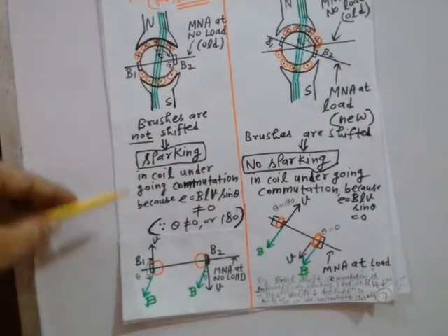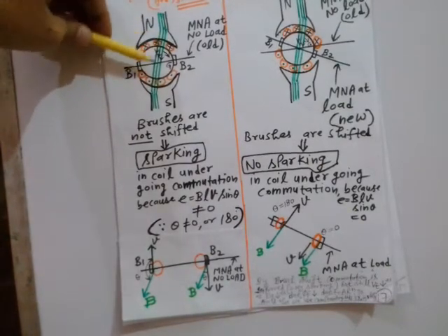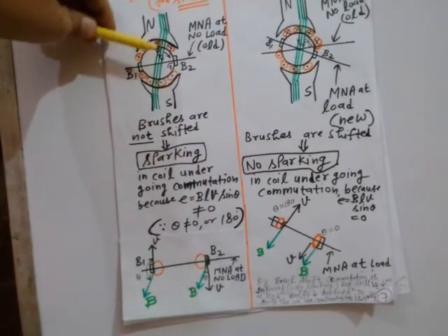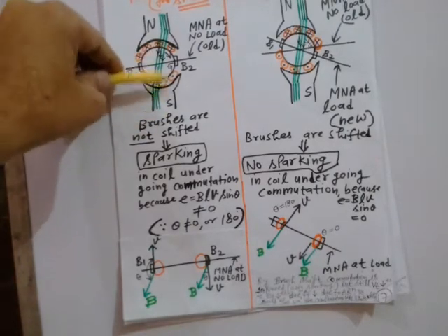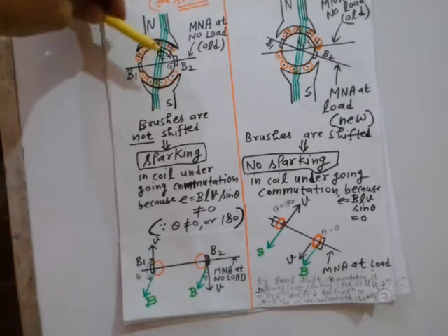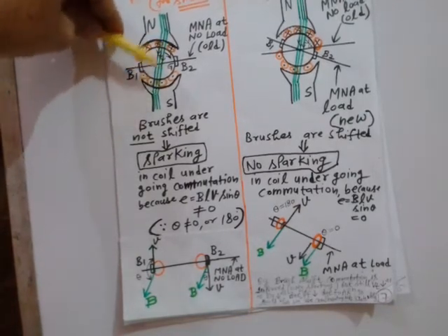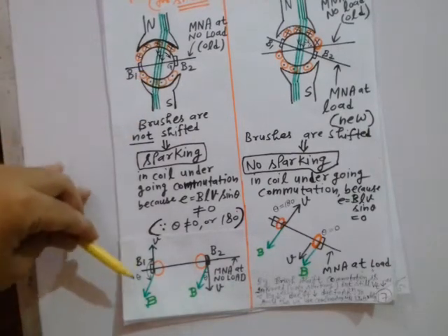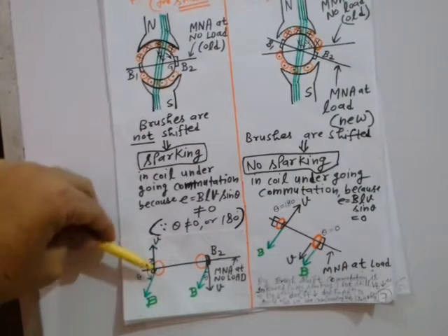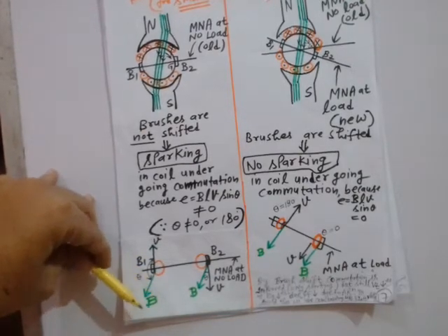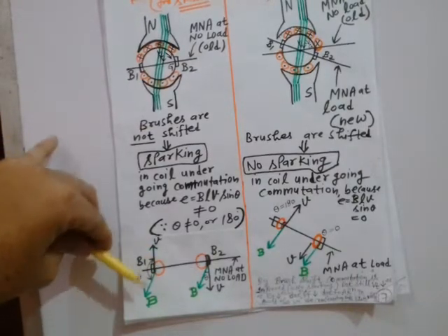Now tell me, what is the direction of field lines? See, the resultant field has now tilted. So this is the direction of resultant field lines. It is tilted. It is not straight like this. It is basically tilted like this. See this. Due to the effect of this armature flux, it is tilted. So now the direction of main field lines is represented by this green. B is showing the magnetic field lines, which are tilted due to the effect of this armature reaction.